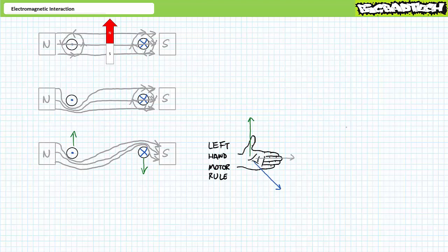While it is entirely possible to explain this interaction using our previous understanding of current magnetism, it can be more succinctly explained using Fleming's left-hand motor rule, which uses the open and outstretched left hand to illustrate how a current-carrying wire in a magnetic field feels a resultant force. Extended fingers of the open left hand are oriented to the magnetic polarity, pointing north to south. The open palm is oriented such that conventional current leaves the palm. Magnetism and electricity interact to create movement. This is motor action. The outstretched thumb indicates the induced direction of movement.